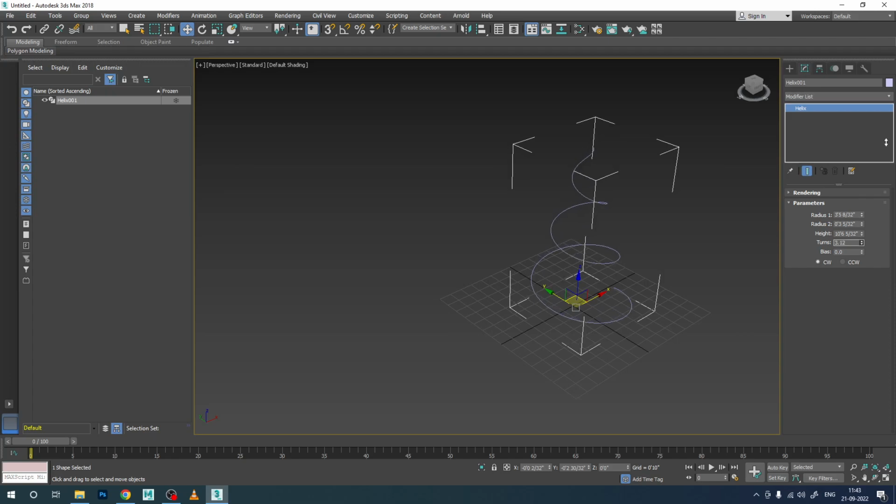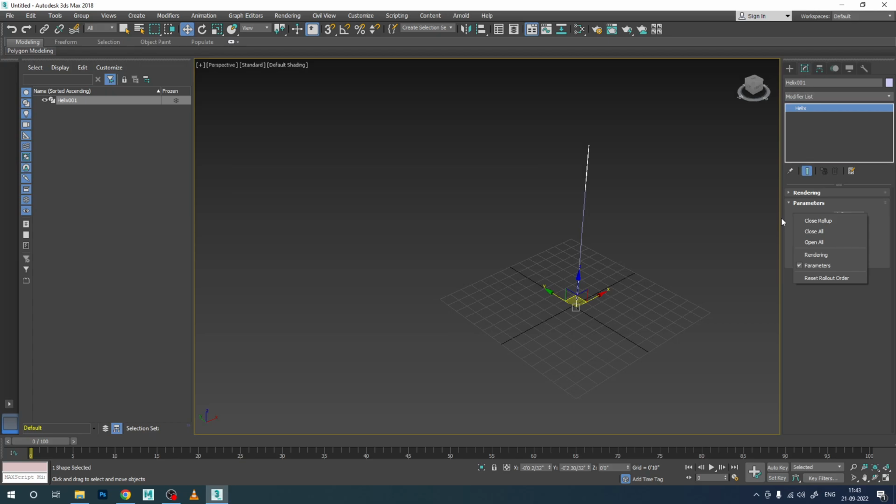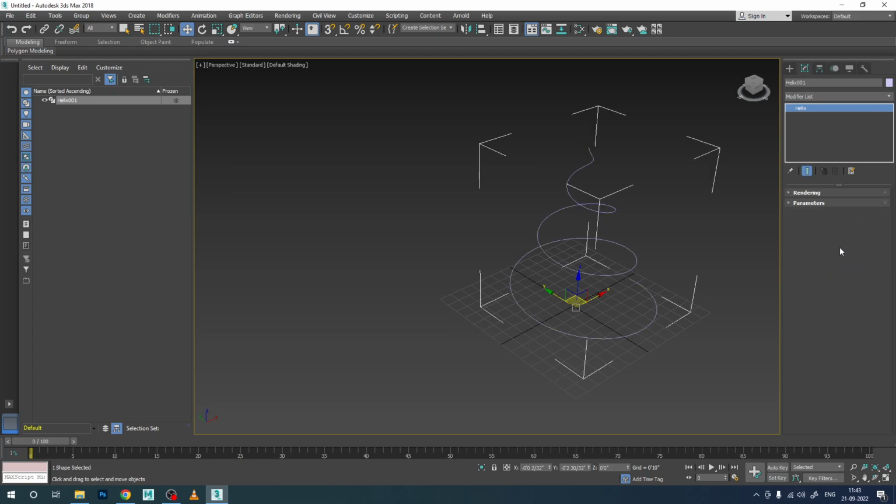Now one more option is there here. For example, if you want to create any shock absorber type object, that is straight from top to bottom, it is the same only. There won't be any difference in this now. So for this one we need to give both radii the same value. So right click on this one and right click on this one to define a 0 value. Then I'll increase this one to around 5 we can say, and go.